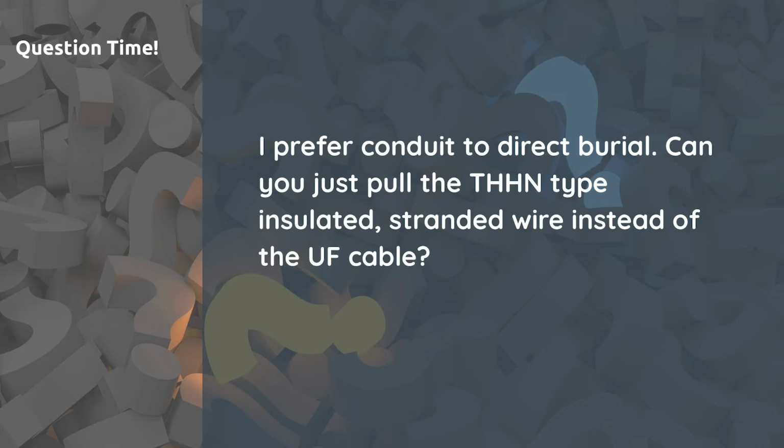He starts out with a bit more of a comment, but he prefers conduit to direct burial, and asks, can you not just pull THHN type insulated stranded wire instead of the UF cable? He says it offers more protection and is easier to make modifications to the system in the future.